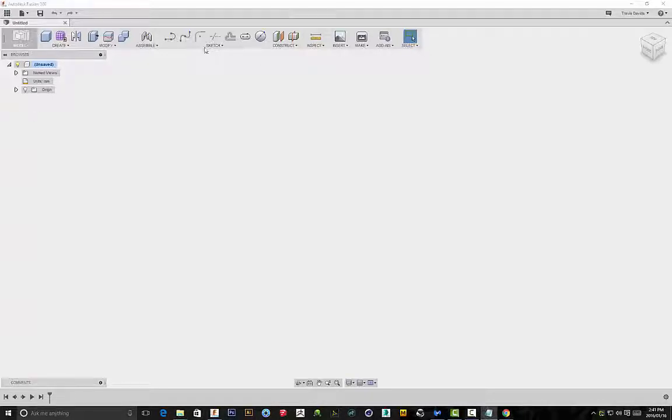So what we're going to be doing is we're going to be creating a sketch, one sketch profile. And the reason why I'm going to be creating one sketch profile, I actually saw this technique online, but when you create one sketch profile, it enables you to select different points of your loft, which will allow you to dynamically change the shape of the loft that was created.